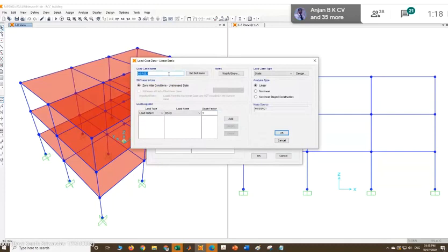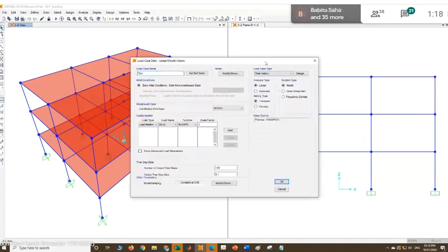So we'll go to time history analysis. What kind of time history do we want? We can do linear time history, non-linear time history, and there are so many options in it. Let's go to linear only. Since the time history which we have, which we generally use, is acceleration time history, I've selected acceleration, and then in which direction? Let's consider the U1 direction, and then TH1, the time history which I assigned. The unit is in terms of g, so I'll apply a scale factor of 9.81.